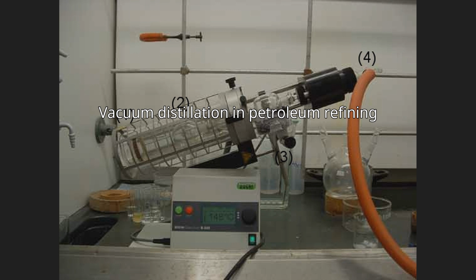Figure 2 is a simplified process diagram of a petroleum refinery vacuum distillation column that depicts the internals of the column, and Figure 3 is a photograph of a large vacuum distillation column in a petroleum refinery. The 10 to 40 mmHg absolute pressure in a vacuum distillation column increases the volume of vapor formed per volume of liquid distilled. The result is that such columns have very large diameters.